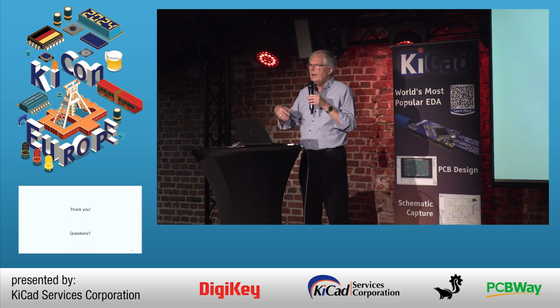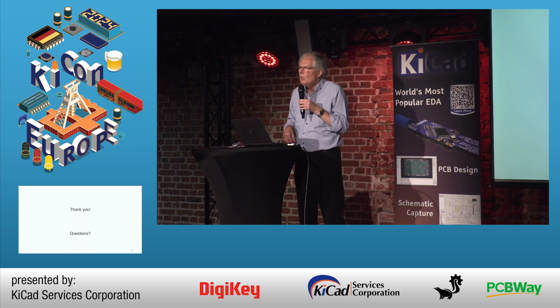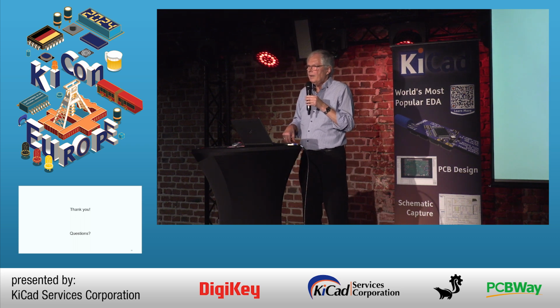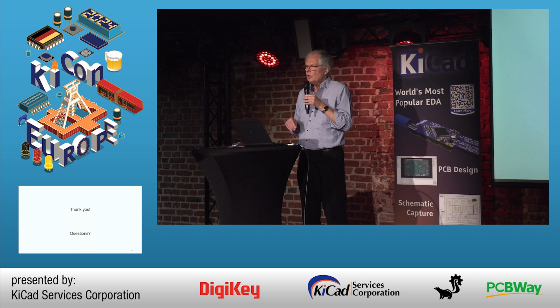So you have to calculate the parameter shift and then just do normal simulation. There are models available, and people are working on new models to calculate this parameter shift, for example by running a circuit for 10 years under specific conditions, seeing what the parameter shift will be, and then resimulating. I think this is possible.